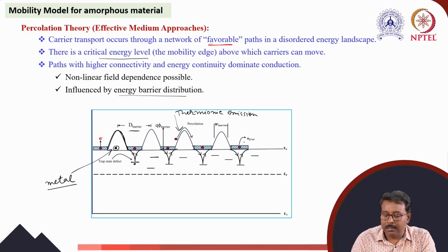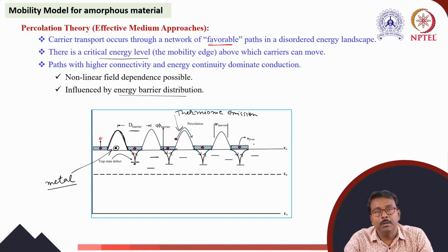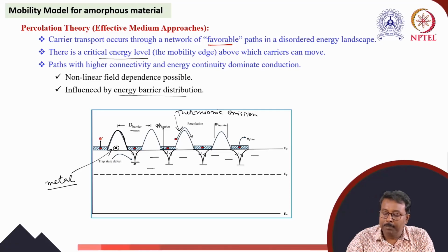If you increase more and more metal in zinc oxide, say, to increase carrier concentration, it becomes more conductive, but it may affect mobility in the reverse way. More and more barriers will be present in the conduction band, and due to that the motion of carriers will be affected. And this can be modeled by just multiplying two factors.